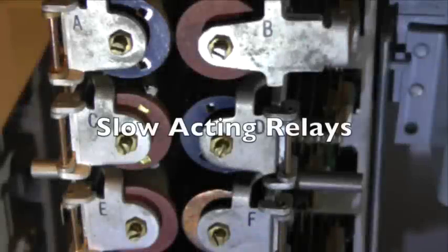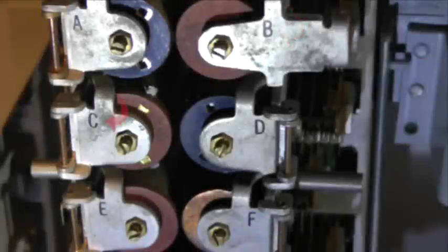There are 3 slow release relays in the connector. These are the B relay, the C relay, and the E relay. A slow release relay is designed to allow the relay to remain operated during short interruptions to its energizing current, or to delay its release to ensure that some other pertinent circuit event has had time to fully complete.